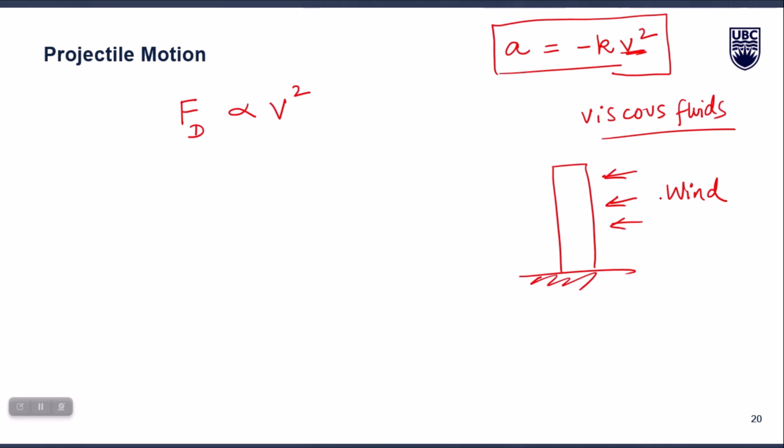And the wind forces, if I call them F, are proportional to how fast the wind is blowing, right? So generally that F is proportional to V square, where V is the velocity of wind, right? Obviously this F depends on other factors like how big the structure is, how much size of the facade of that building is, whether that outer surface is an open surface or is closed all around and all that. But mainly that force would depend on scale of the velocity.